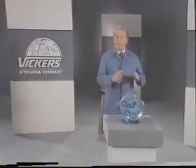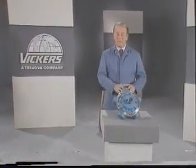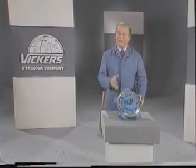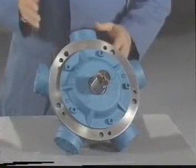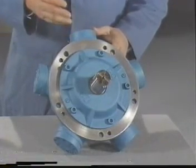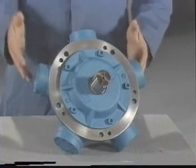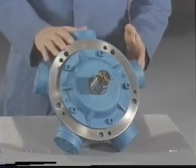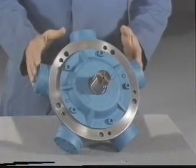Radial motors, while not as common as those previously mentioned, are found in applications where low speed and high torque are needed. This type, which is often used in applications such as an injection molding machine, has a maximum speed rating of 100 RPM and a maximum torque rating of up to 16,000 pound-feet. The capabilities of this type of motor often eliminate the need for a gearbox.